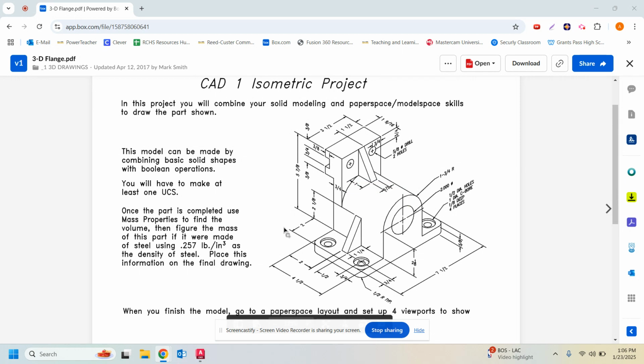We've got some holes on this side. We can infer, and well, we don't even need to infer because we see the arrow, but there's going to be a matching hole over here. We've got our face. This face is really made up of, you could make it a couple of ways. I'm imagining we're going to do a rectangular prism or a box shape that we will either fillet round or we will use a circle shape and make that a cutting tool for us, which we'll get into later. We've got another triangular prism or